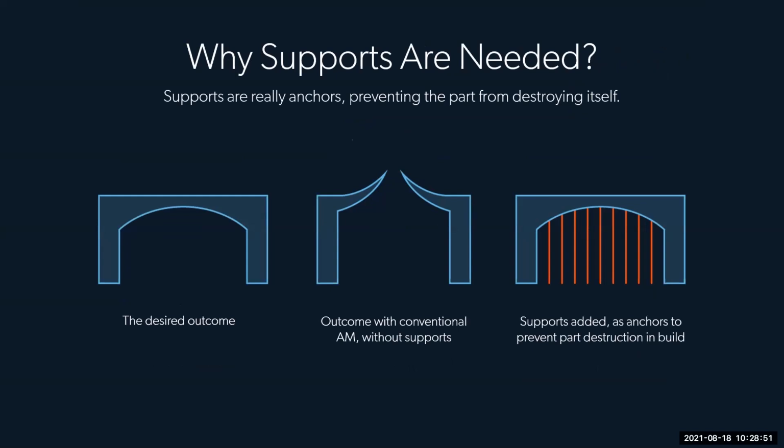So for traditional 3D printing, supports are common as a necessary evil to make some geometries printable. We're welding metal, so we're introducing a lot of heat into the part, and then that material is going to cool and contract. If you have substrate underneath your current layer, the heat has somewhere to go, and there's enough structure to prevent any severe warpage due to that cooling and contracting. But in the case of an overhang, like shown here, there isn't really much substrate underneath. So in a minor case, you'll end up with a really rough surface underneath there.